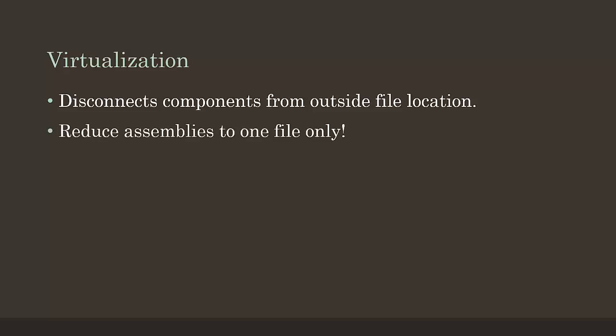It reduces the assemblies to only one file, so that's kind of nice. Yes, the file size does get larger, but here's the argument that I've gotten into. Where I used this was when I would go to Bimba and get an air cylinder and download it. It's the most beautiful air cylinder you could get. It's awesome. It's great. It's got all the wipers and the rings and the bolts and the nuts, everything I don't care about. And what I hated about it was that it was the one assembly I need and these 30 other parts that I don't care about, but I had to now manage them.